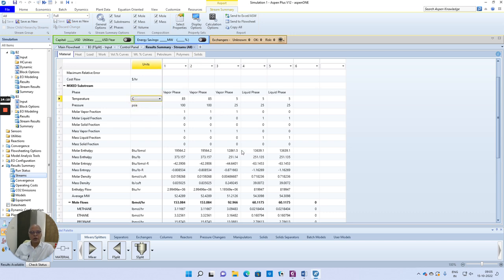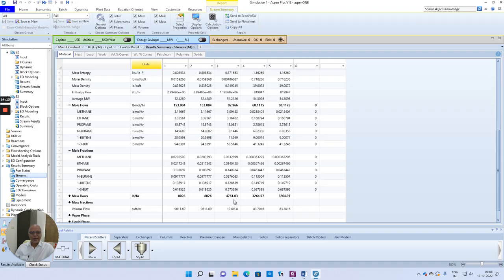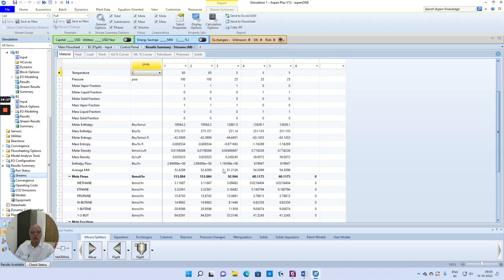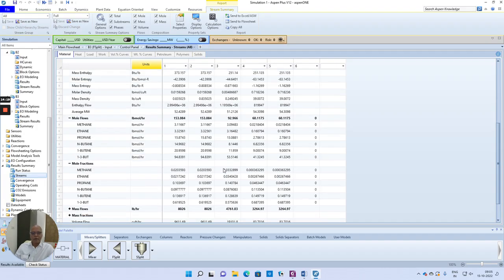So now in order to get an amount of 180 lb per hour in the top product, what should be this temperature? Now you can analyze and see that when the temperature is 5, we were able to get more than 50% as vapor product. But if you want to get something like 180, should the temperature be more or less? So that you can analyze. Accordingly, you can think of using maybe a design spec in order to obtain whatever is required.